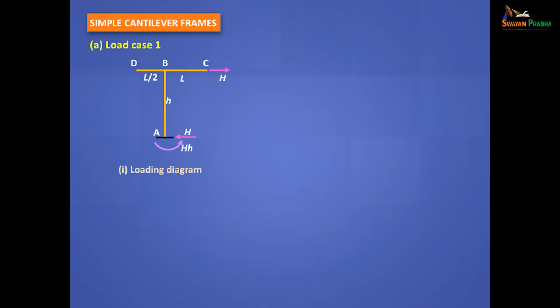Well, go to your support reaction. If you have load H acting there, horizontal reaction to the left H here, moment is capital H into small h, right? Then draw your free body. There are 3 free bodies. You can separate them up and you can start anywhere.